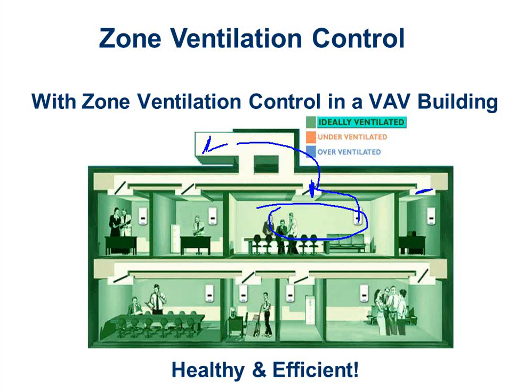The minimum, and maybe I could probably try to explain this. So when you look at ASHRAE 62 or the mechanical codes, on a current mechanical code, you have to provide a CFM per person plus a CFM per square foot, right?